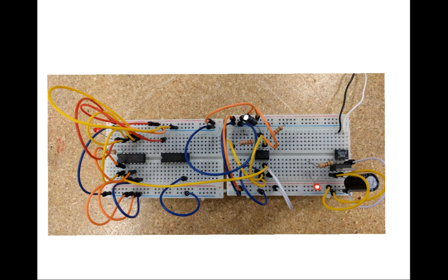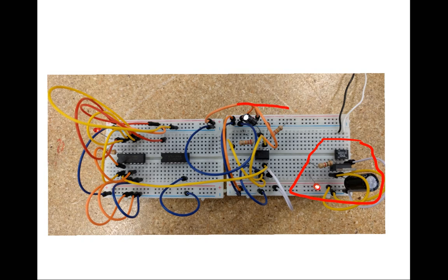This is my design of a very simple counter. This is, I think, the ripple counter. Let's take a look at it. We have the power supply over here. Here's the 555 timer sitting in here, and we hook pin 3 of the 555 timer, bring it over here and drop it into the clock on this flip-flop. And then this is that dual flip-flop through here. Notice that the edge of this is right up here. That's that little notch I talked about.